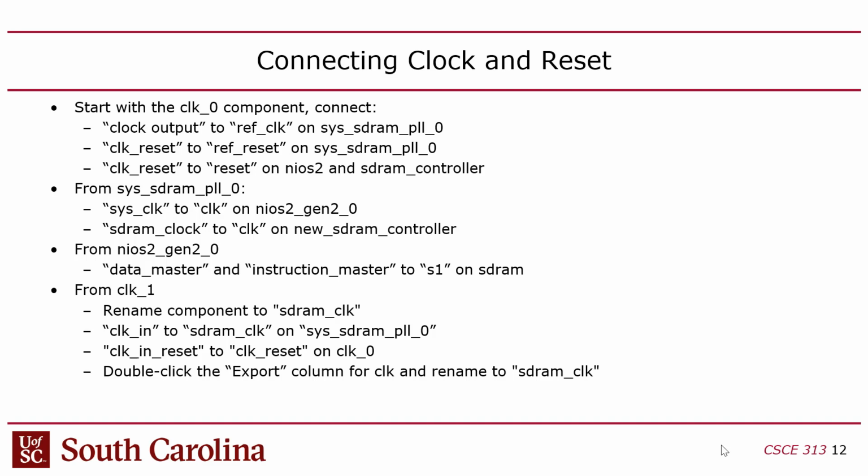Okay, so that's the reason why you have to jump through some hoops to set this up. By the way, that SDRAM clock goes straight to the SDRAM chips. You just export it right out of the FPGA, and it goes directly to the SDRAM. But if that's on the same phase as your system clock, it causes some kind of timing issues, which are not apparent until you start getting glitches and bugs, or it misbehaves. So that's the reason you have to have that.